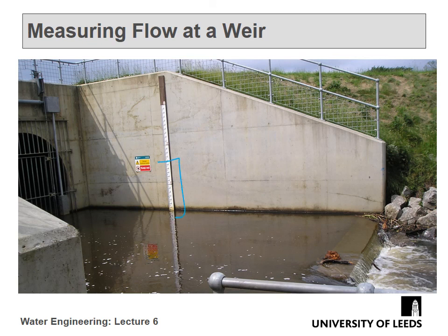This is a river measuring the height. This is not very high, it's 1 or 2 centimeters. But once the flow is up at a greater height, they're very interested in how much flow is going over this weir and down the channel. They're not so interested when the flow rates are low. But all this is got from just measuring the scale on this ruler and using the weir equation.